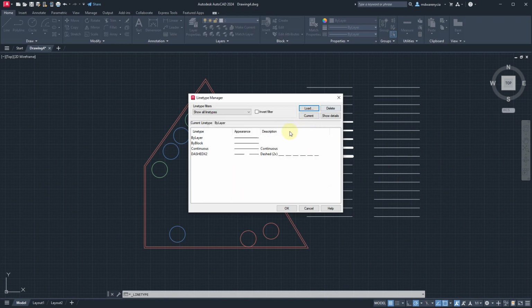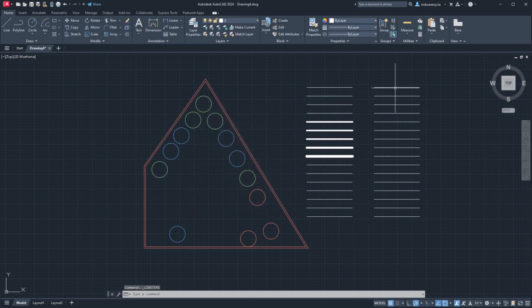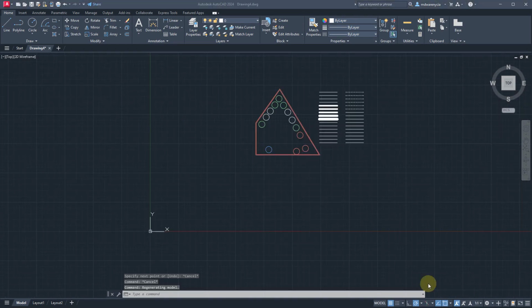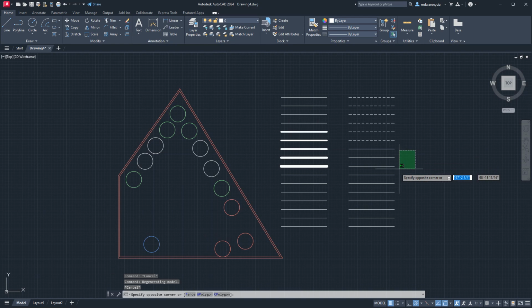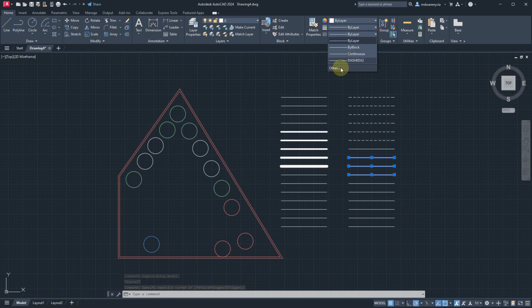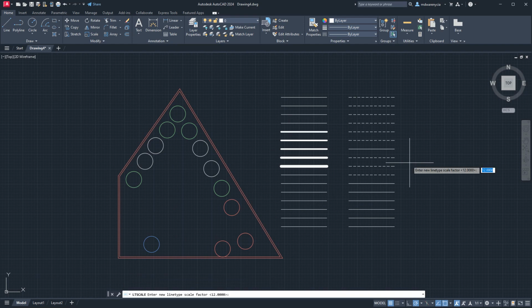So if I was to load this one in, let's grab this whole chunk right here, set it to 2x, and again, it's not going to show, and I always get confused on which one to do. Okay, yeah, I had to look it up. It's LT scale, so it's one of those commands where you set it once and configure it in your drawing. So anyway, when you place these lines down, if I choose LT scale, you guys right now have 1, so you aren't going to see those, right?